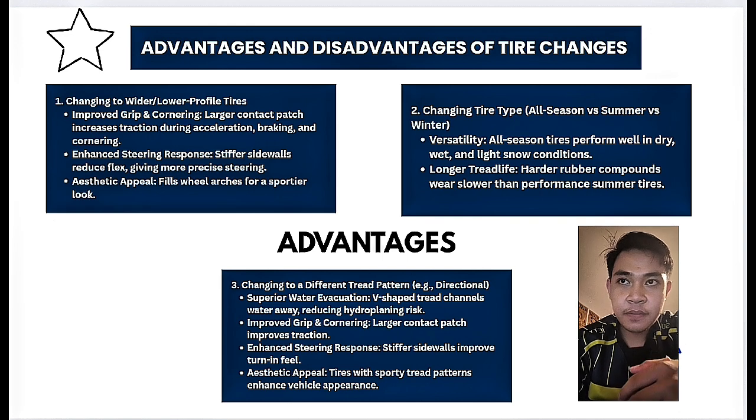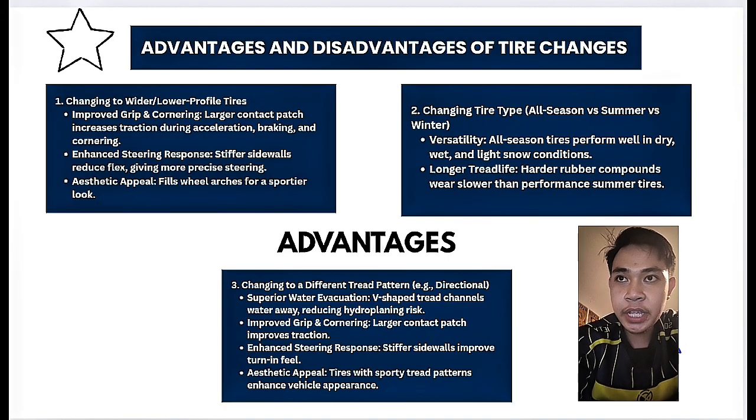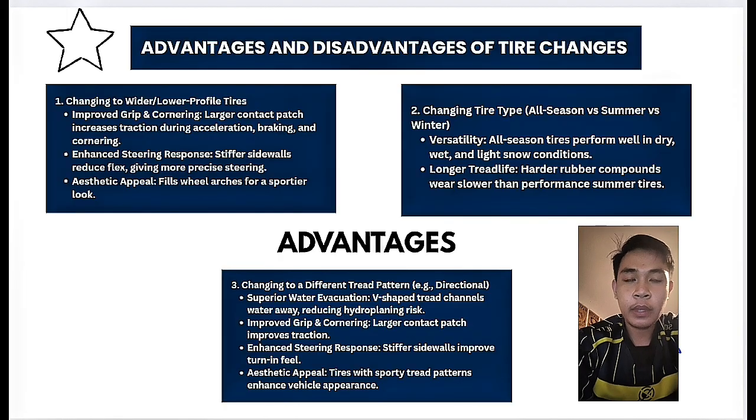The advantages for changing to wider or lower profile tires is it improves grip and cornering. Larger contact patch increases traction during acceleration, braking and cornering. Next, it's going to enhance steering response. Stiffer sidewalls reduce flex, giving more precise steering. Next is aesthetic appeal. It fills the wheel arch for a sportier look.